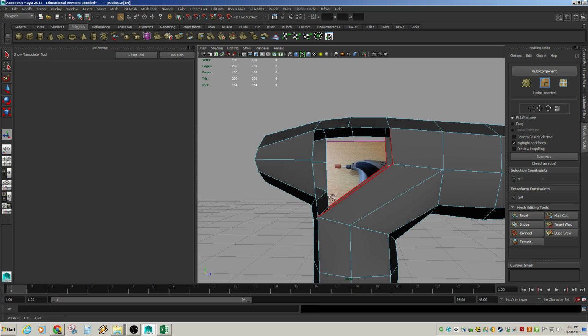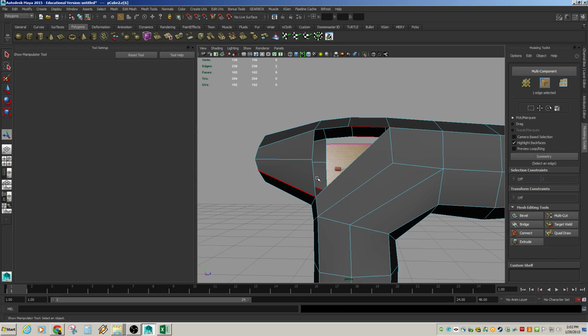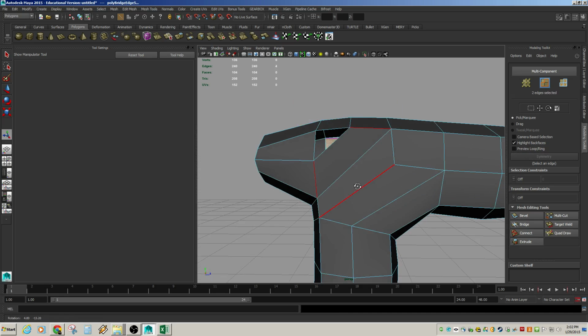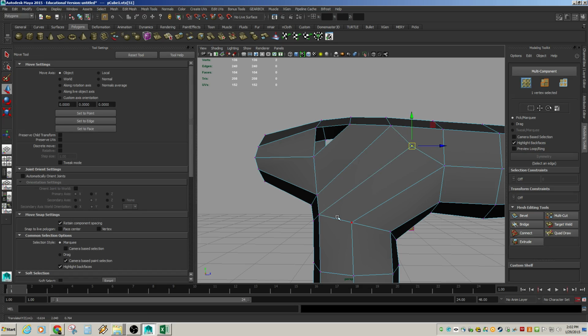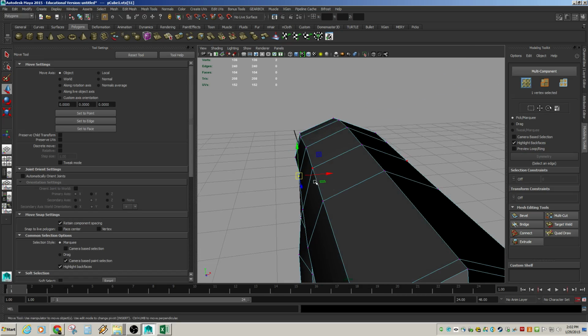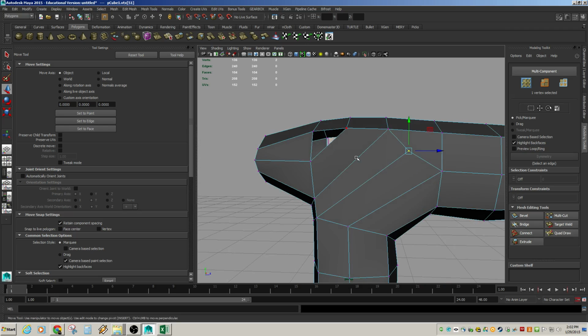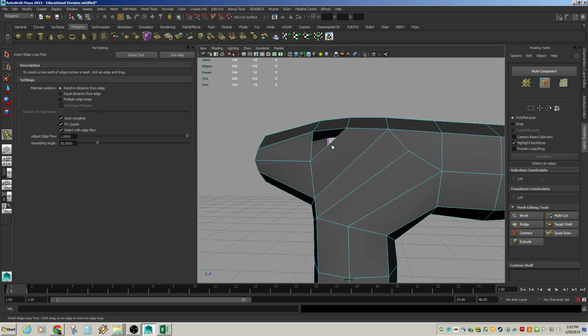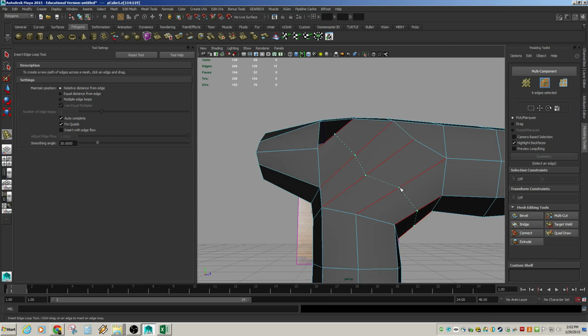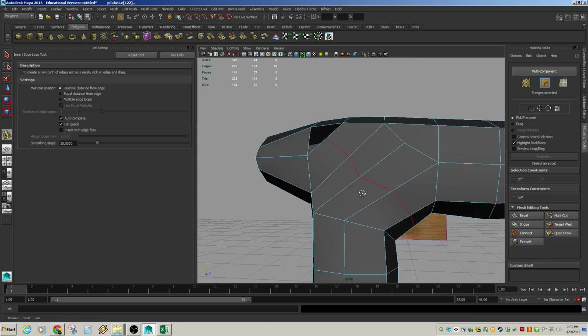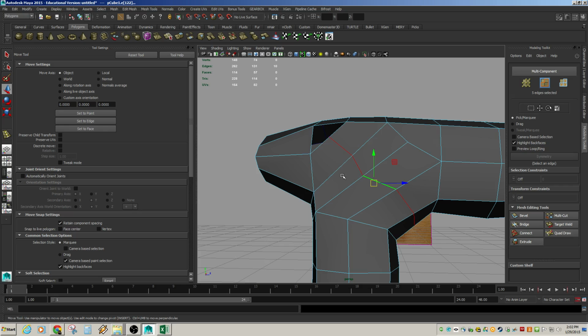And we're going to end up with some weird flow here at times. Oh, there you go. Right, because we have this triangle now. But again, a triangle is really just one step away from being a quad, right? So I could insert an edge loop here. Right. Let's turn off that insert with flow. So I'm inserting an edge loop, and now we have that in there.